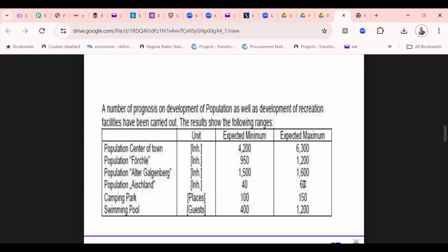Or if I'm doing a water design and I'm looking at a rural area, it cannot be the same as the one I'm doing for a place that I know the city is going to grow. Let's say there's a university built in Wawalada today, and I'm asked to do a water reticulation for that area. I know that with time, houses will spring up. So if I'm using a population growth, I can use, say, 5%, 10% or higher, when the Nigerian average is about 3.5 or 4%.